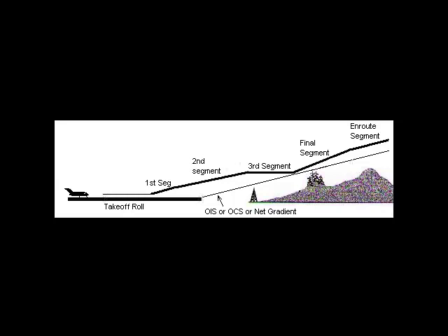Simply put, if the one-engine inoperative procedure does not utilize this methodology, and you simply rely on maintaining second segment configuration indefinitely, any performance numbers derived from the AFM are meaningless. It is the complexity of calculating this geometry to stay above the obstacle identification surface that makes EFB-Pro so extremely valuable to you, and the reason simplified tab data, FMS values, and airport familiarity do not work.